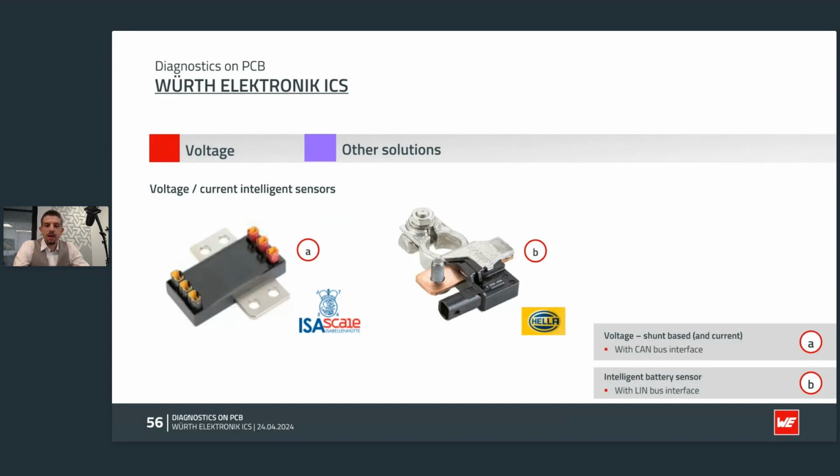Those sensors often communicate directly over CAN bus or LIN bus and do not really have their place on our power board. But I wanted to give you a good overview of the diagnostic solutions we discussed with our customers. In some cases, we still implement the diagnostic of those sensors directly on our controllers. We are then speaking more about communication diagnostics than physical values. We diagnose whether the communication with the sensor is successful or not, and return this diagnostic to the main interface, along with all the other parameters we are watching on our power boards.